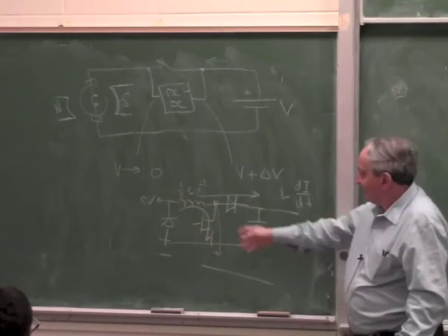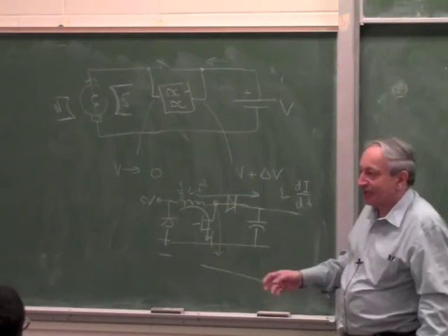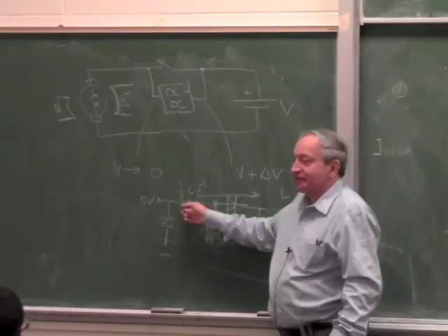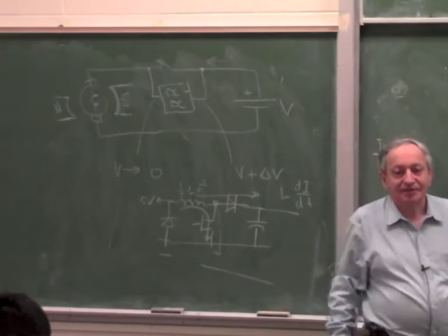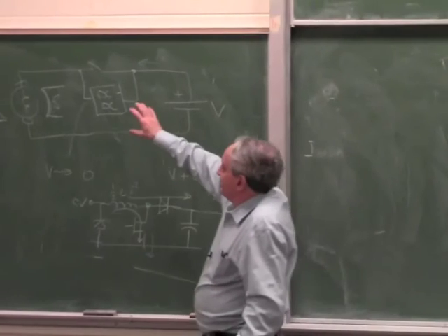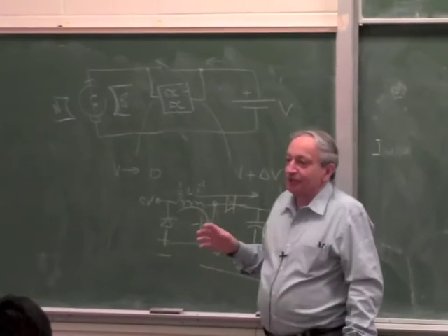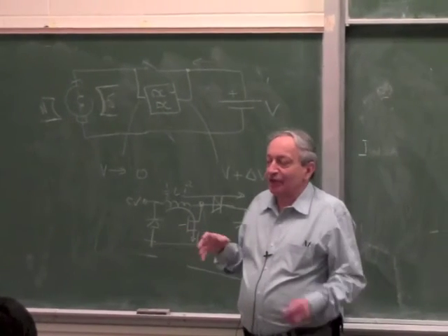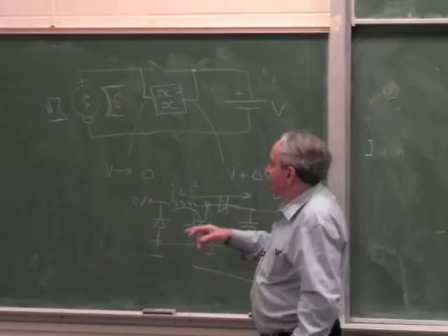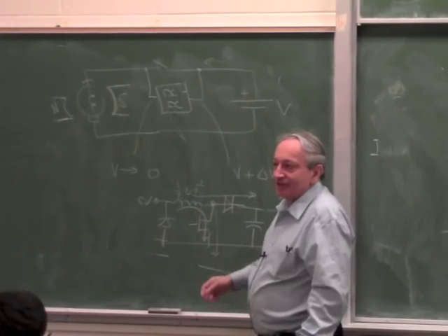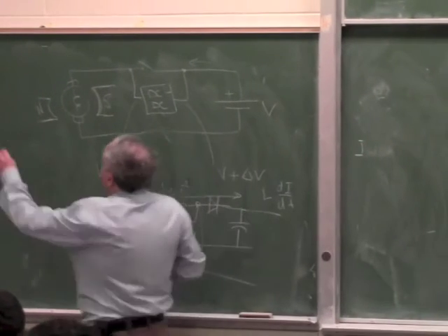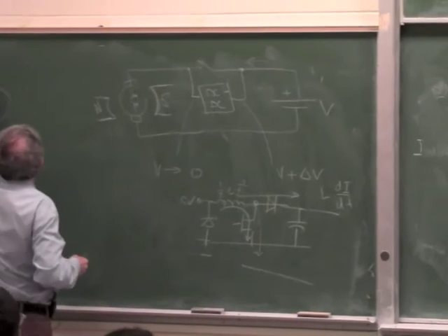So that's one of the simplest converters which can take any DC voltage and make any DC voltage out of it, just with two components. Okay? So if you put this thing inside here, you have regenerative braking, which is very good. And the servo amplifiers, which are designed for higher power servo systems, incorporate that. Okay? Good. Now, if there is no magnet, but there is just a coil, it still works.